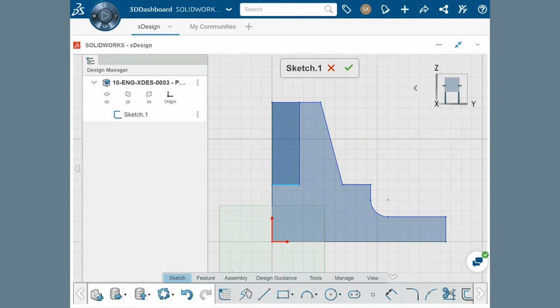And now these lines will remain collinear with one another, no matter where they're positioned. This vertical rod mount will be created using a revolve feature, and this thin rectangle will create the cutout where the rod fits into place. The design intent of this part is to make sure the cutout is half the diameter of the top face.